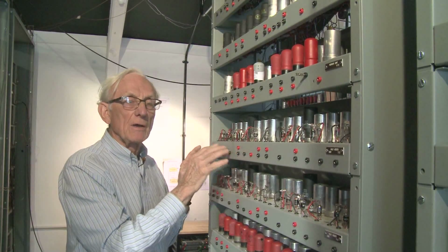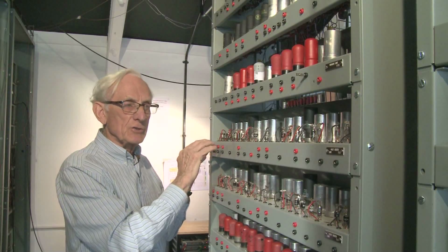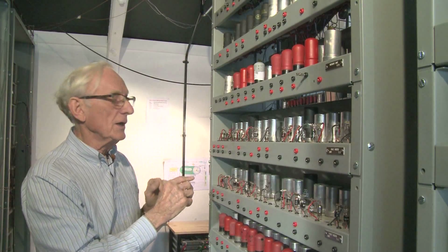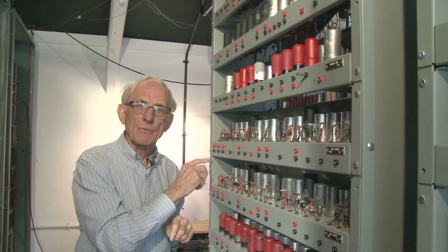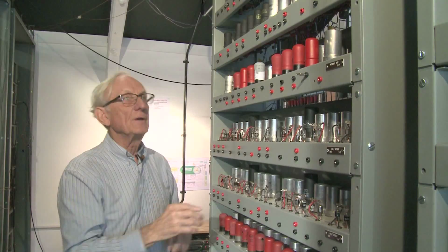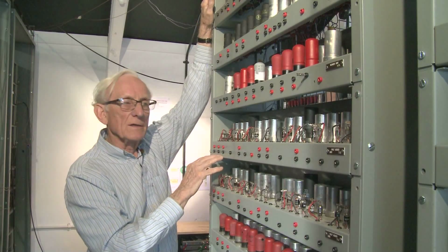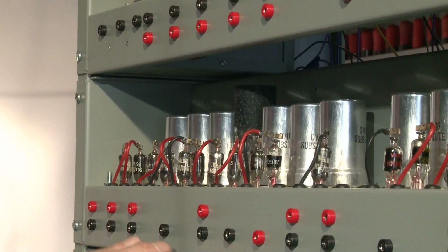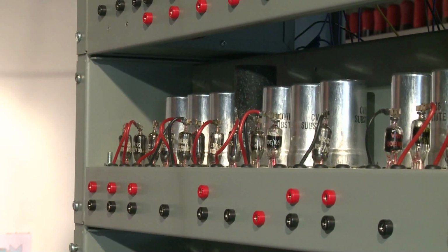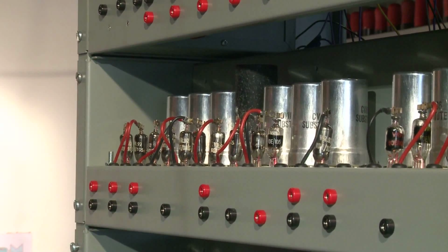And so it's simpler, it's a half adder, and just one chassis is enough to do that in conjunction with the memory tank. And every time we add a 1 at the bottom of the word, that increments the number in the tank. So the counter tank is having its count incremented every minor cycle, every 18 bits.